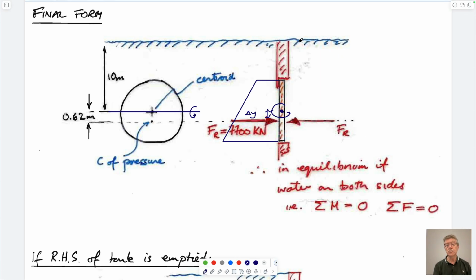Let's drain the other side, and let's put a backstop here. So we know that when this force goes away, because we've drained this side to this, then this gate will tend to be pushed by this force. There's nothing acting on the other side, so it'll tend to rotate like this. And so if there's no backstop here, it will just fail and all the water will escape.